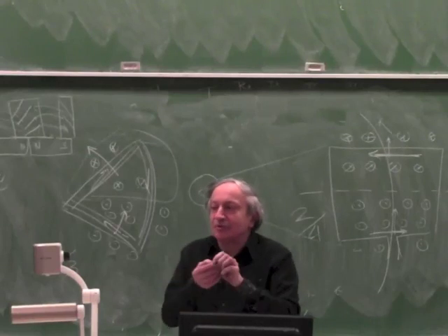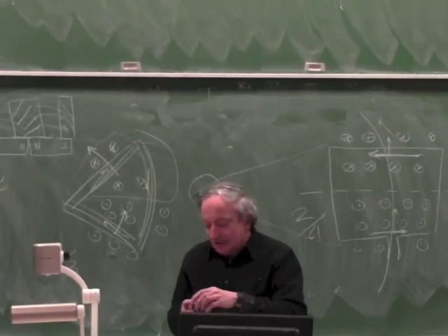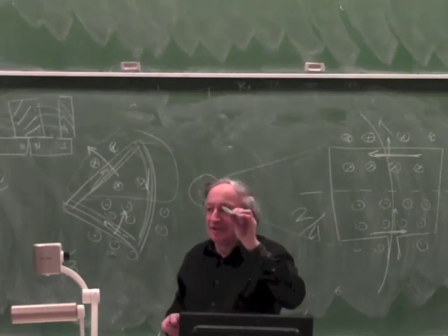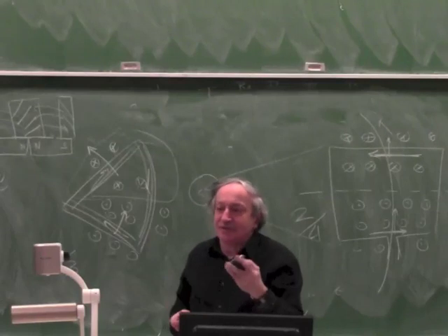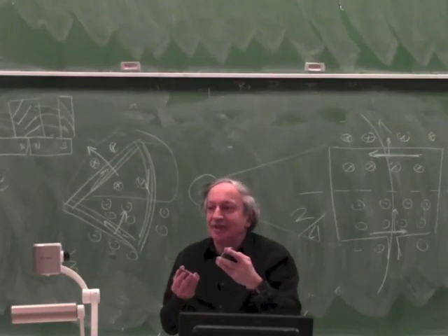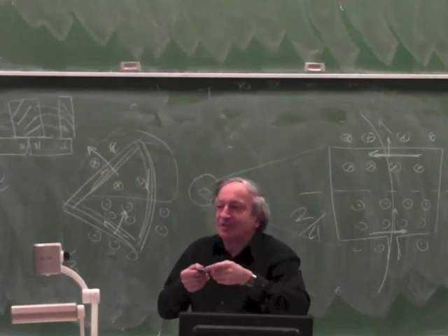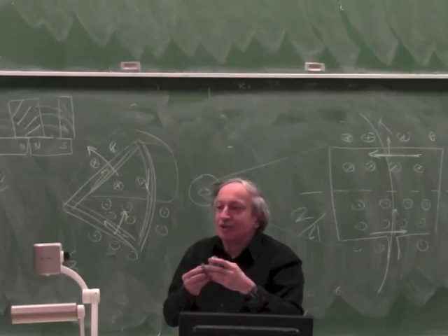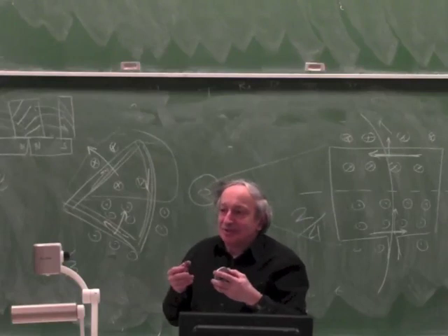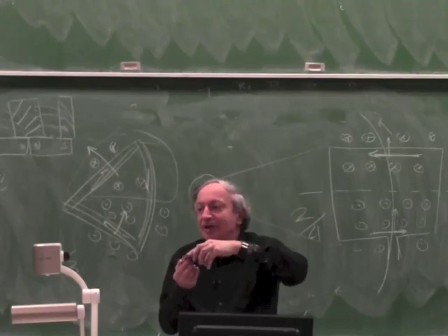One is a standard DC motor which has coils moving in a magnet, and one which is inverted, where there is a stationary coil and a moving magnet. That's from a floppy disk drive, which is obsolete, but in the floppy disk drive they use a moving magnet because for some reason it was beneficial to do it this way. They wanted the big hub to support the drive. You can say that's just like a brushless electric motor. But in a brushless electric motor, like a stepper motor, the armature is a magnet, the inner part is a magnet. Here they just made it the outer part.